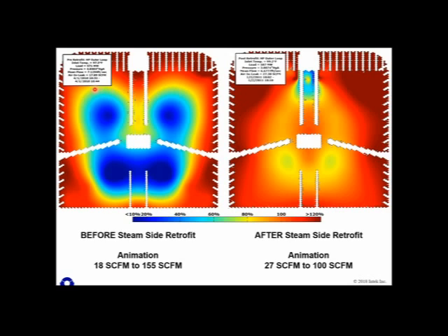And this is the way this Ingersoll Rand has always operated since the day it was installed. The reason for it is that they only shrouded the one bay in the unit. They didn't shroud all the bays, so it allowed the air to build up in all of the bays except the first bay. It's a catastrophic design oversight for this condenser, but it was part of our effort to implement a strategy during the REAP tube to correct that air cooler section.